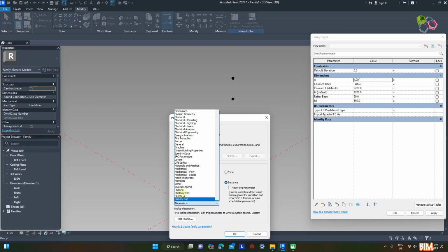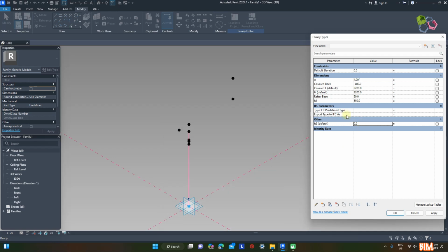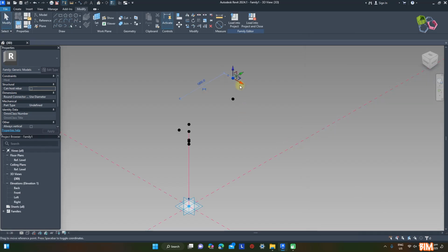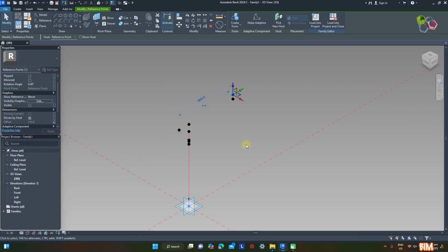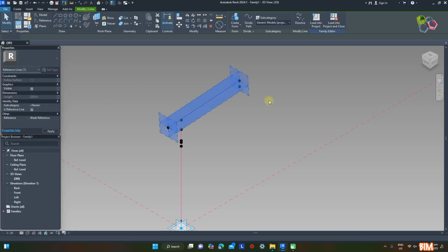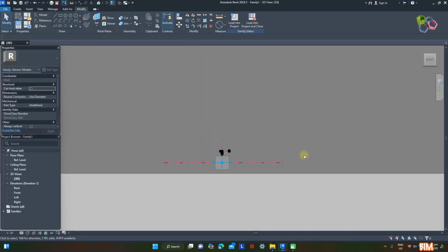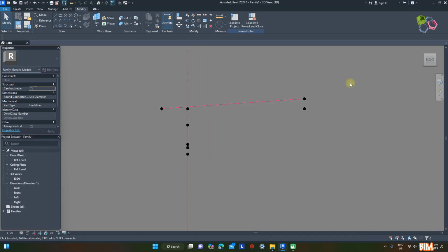It is introduced along with a formula to calculate the vertical offset h2 for the roof slope, allowing dynamic adjustment. As I know the angle A and the adjacent side, I apply a simple trigonometry formula: covered length times tangent of angle A. This gives me a computed offset value to raise up this point. The point, linked to parameter h2, connects with the point behind, made as a reference line. Let's see from the side elevation.